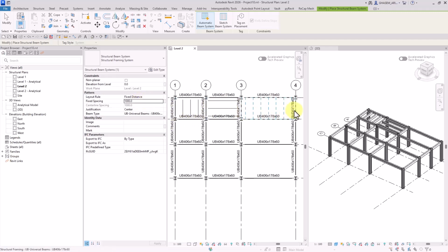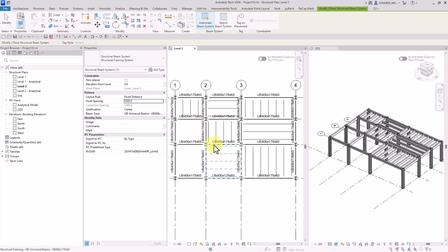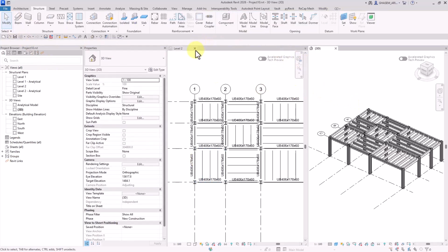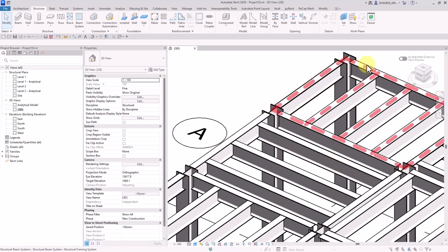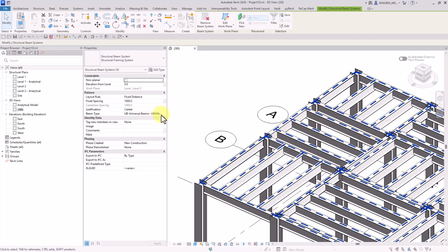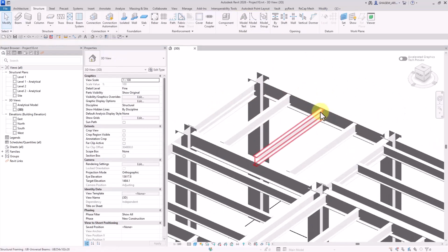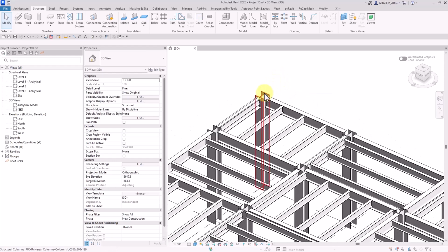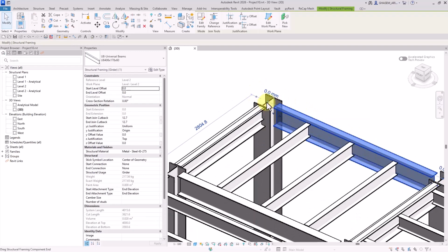Now guys, when we do this, by default, the software would automatically cut these elements inside our project or model. Let me try showing this to you in 3D. See, these are automatically cut. I'm going to select this beam system, right click, and select the entire project. And for example, we can select another type. All right, good. Now guys, when we say point-to-point modeling, we mean that we actually need a starting point and an end point.